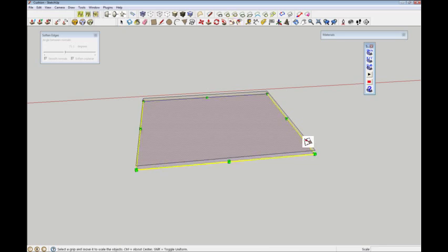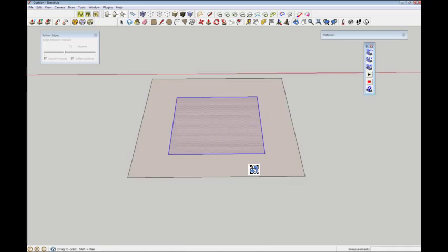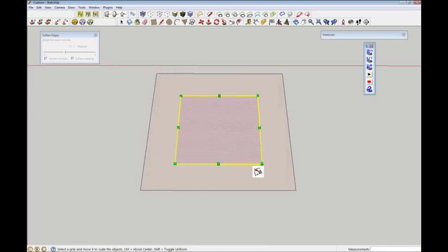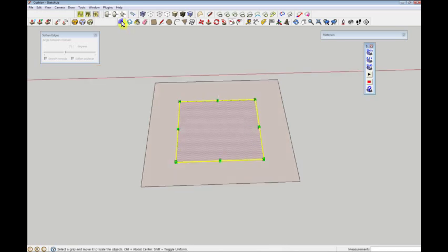Get the scale tool, grab it on the diagonals, press Control and then hold down the left mouse key and draw that in so it's whatever size. It's not really that important at this time. That will actually be the size of your cushion. So if you want to make it a correct size, you just have to put the size in the bar, and you must put millimeters when using the scale tool, or whatever measurements you're using. You must put it otherwise it won't work. It'll think it's a scale ratio. All right. Now we've done that.